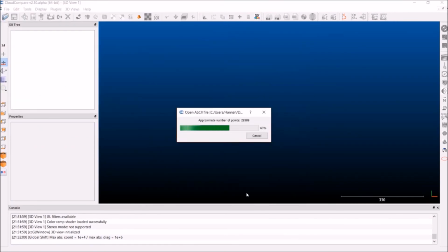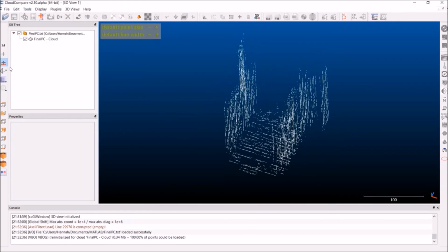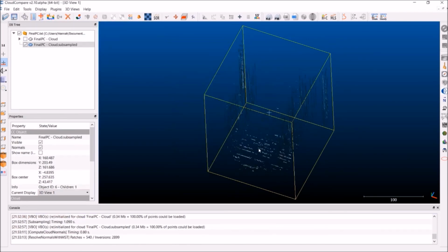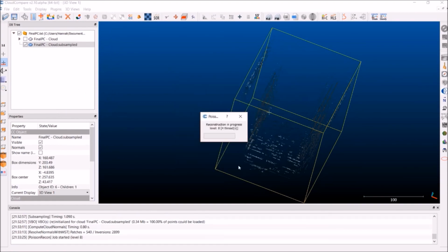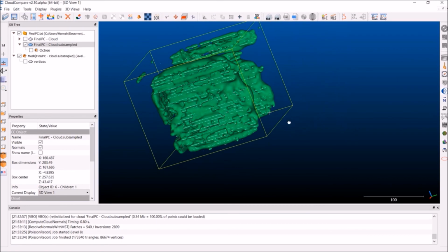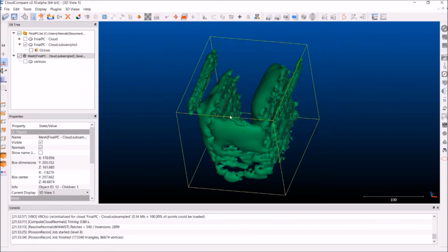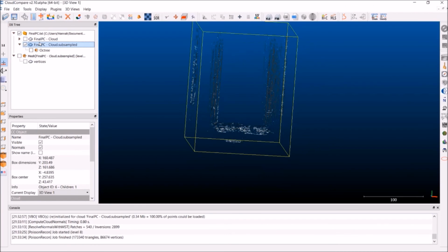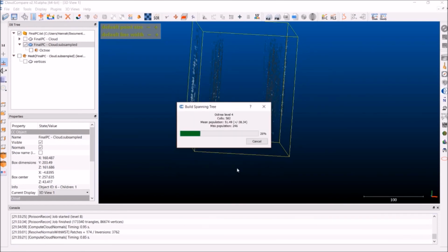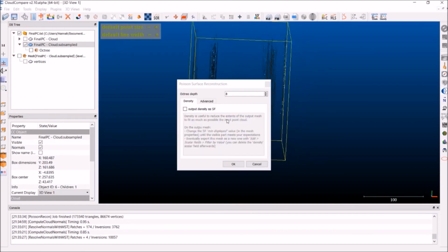To begin meshing my final filtered point cloud, I first imported the point cloud into Cloud Compare. I then computed the normals for the mesh and used the preset number of neighbors, which was 6. I applied a Poisson surface reconstruction to generate a mesh, but the resulting mesh had a lot of empty space, which was anticipated because the points making up the three faces of the ATM are far apart. However, I recomputed the normals, this time with a much higher neighbor number, and remeshed in hopes of filling in some of this empty space and connecting the sides of the ATM with one another.